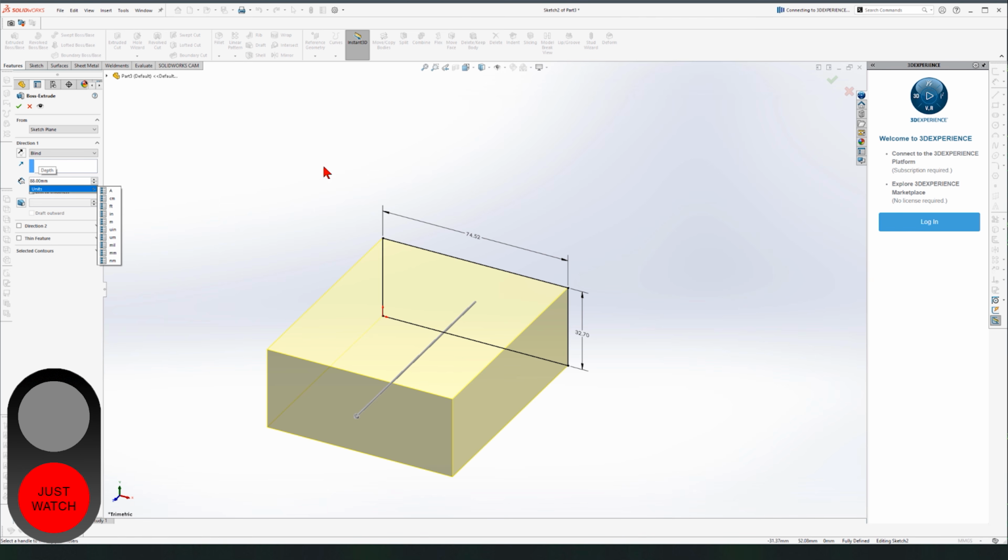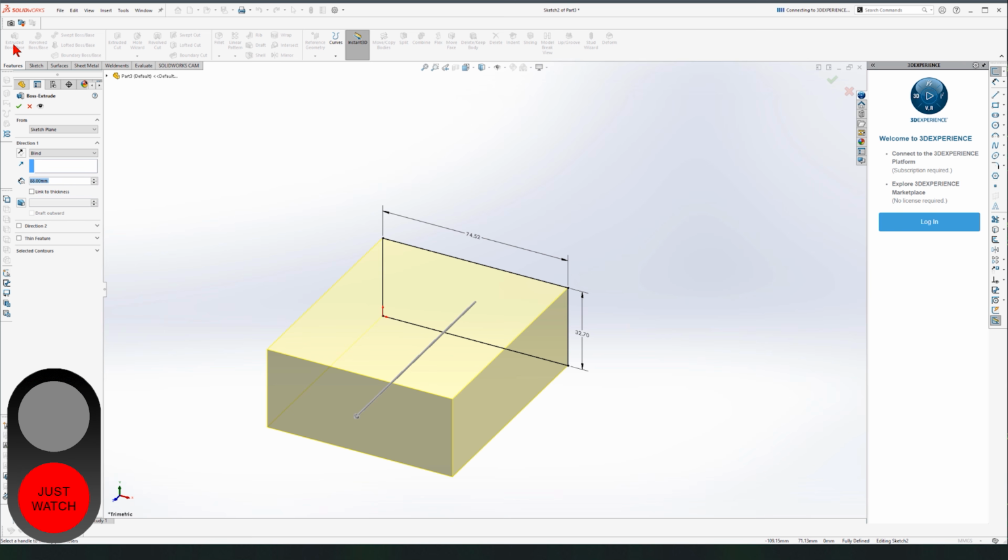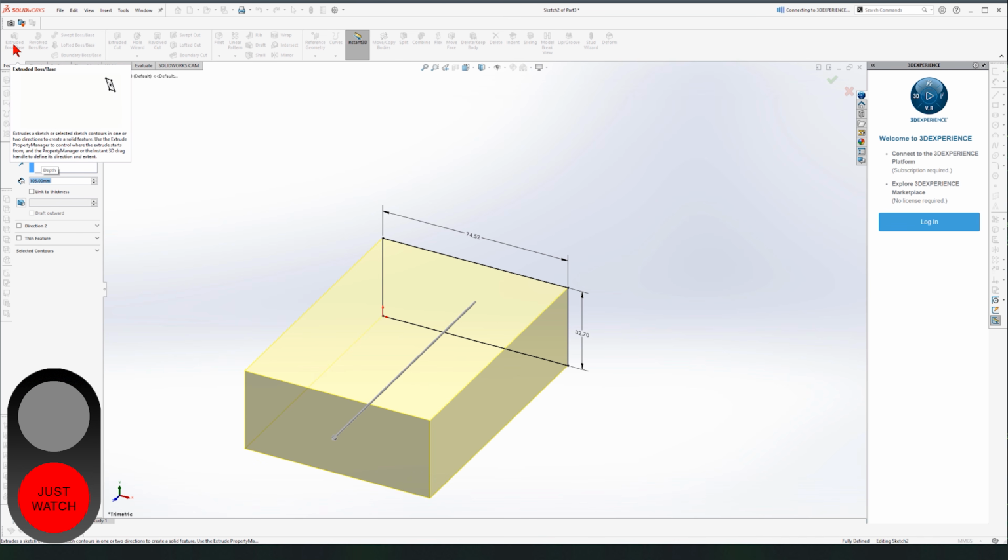You can, but a lot faster way would be just to, as soon as you click this, don't click anything else. Don't do anything else. All you have to do is to type values, numbers like 105. Look what happened. And it has the same unit. One enter brought back the unit. This is highlighted.